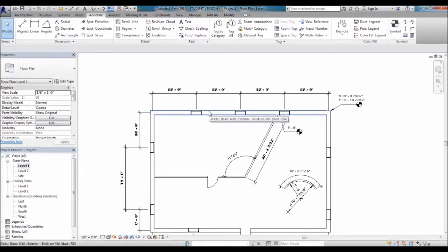If you think of them as CAD lines, what those do is add a little more detail into your drawing, but you're not actually modeling them in 3D. A lot of things, like nuts, bolts, connection details, anchors going into your concrete, edges of rebar, you could technically find a family for them, load them in and actually model them in 3D.